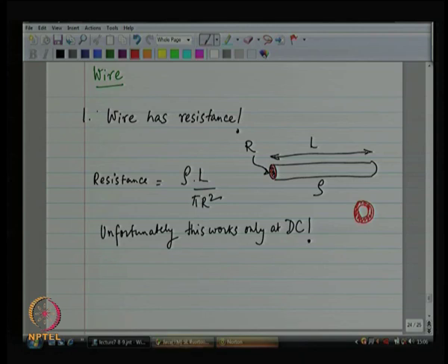So, the cross sectional area of this is pi r squared minus pi (r minus d) squared, that is the cross sectional area, and this gives me my new resistance at a given frequency, right. So, given omega you can compute the resistance.